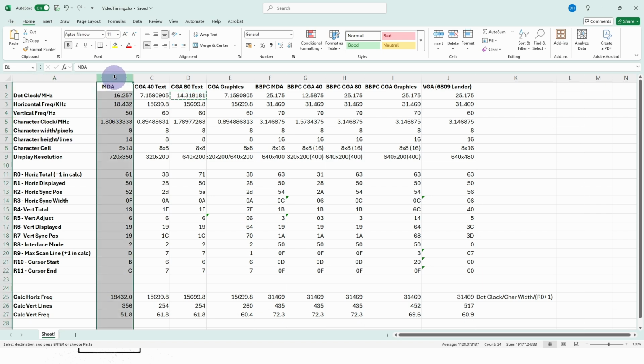Now, the original monochrome display adapter used 9 pixels across, I think because the IBM people wanted to have the characters looking as good for business use as possible. In general, although the VGA will also do 9 pixels across, it makes things a little bit more tricky, and so I tend to stick with 8 pixels.